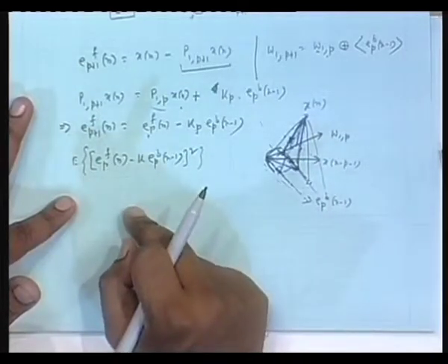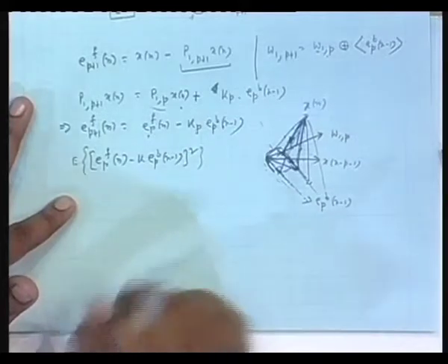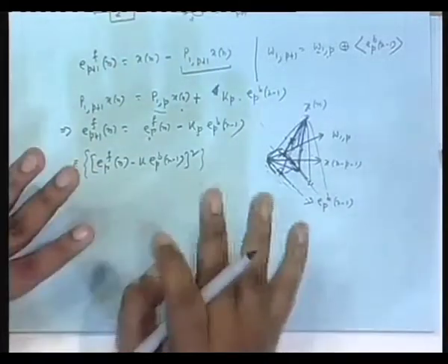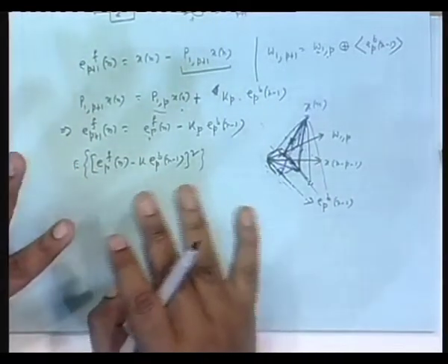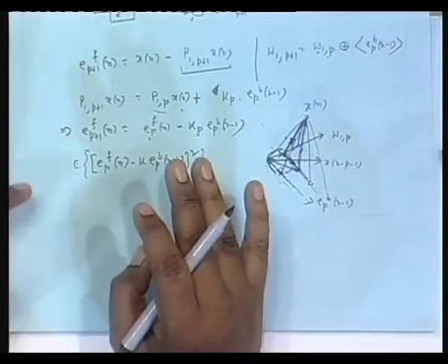Okay. So suppose I carry out a steepest descent now, that I don't know what the optimal k is, like in the case of the adaptive filter. How did we go to the adaptive filter? First we started with the optimal filter, we had the expression R inverse p, and then I said suppose I don't know how to compute R inverse, or R may change from time to time. Suppose I do an iterative procedure, I said the steepest descent search.